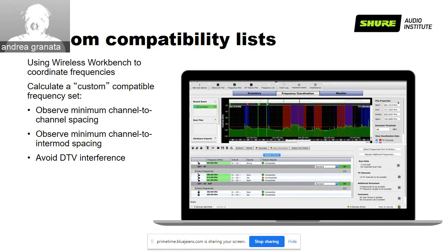But this is kind of a rule of thumb, because at the end you don't have a single tile emitting. You have a wall of LED screens that are making noise. In that case, maybe when all this is over and we will be able to go around easily again, I may prepare some measurements to show the difference between the back and the front. That is still pretty significant. The main emission is not the LED itself, even though it's still emitting something. The main emission comes from a little box at the back of the LED tile.